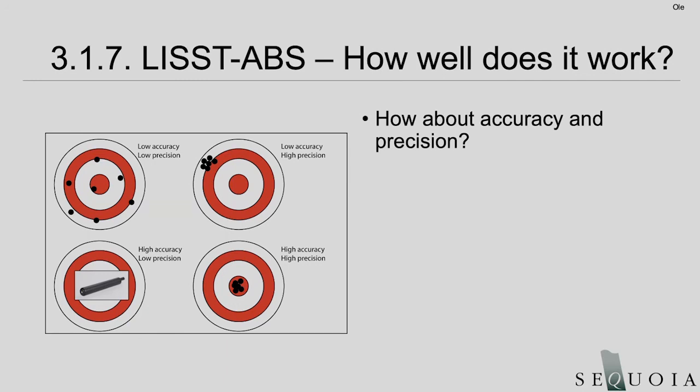And you might see that the 20, 30, 40% variation around a true concentration seems like a lot, but you do have to contrast that with turbidity sensors, who varies a lot more around the true concentration. So a turbidity sensor would really be somewhere in between the high accuracy and low precision and typically the low accuracy and low precision, moving up towards that on a line, depending on how well it's calibrated and how much the particle size has changed since the calibration.